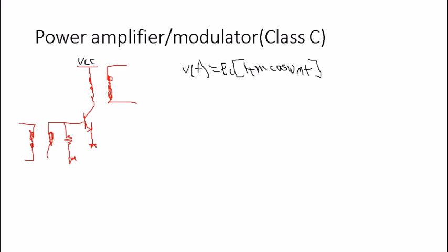M here is defined as the modulation index, multiplied by cosine, again multiplied by cosine omega c of t. The highest number for m can be 1, and the least can be 0. 0 means that there is no information signal in this AM modulation.